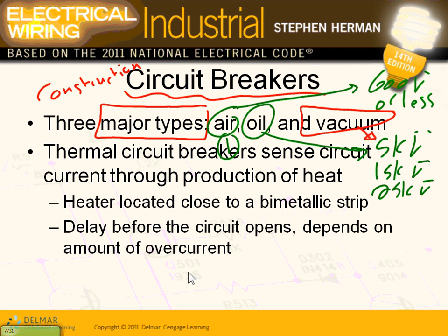Why are vacuums not used everywhere? It's not economically viable to use them. It becomes economically viable in high voltage because the arc becomes extremely severe. In low voltage, there are other technologies available that can handle the problem much cheaper than the vacuum tubes.